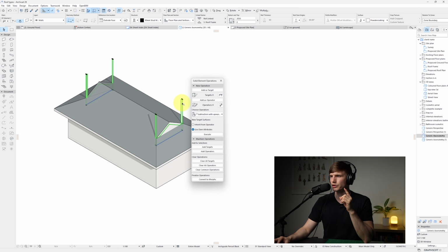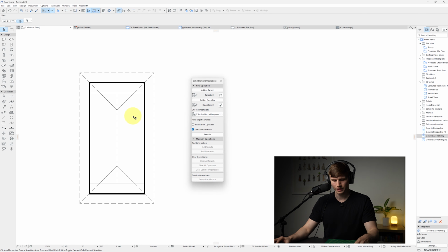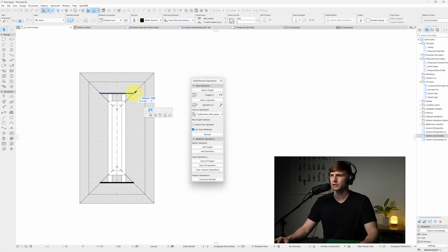Now we've got these little leftover bits just on the sides here, from where the wall is slightly outside of that gable. If we go into our 2D view, and then holding Control, go up, and press the up key. If we select our wall just here, we'll click the edge node, and with stretch selected, we'll hold in Shift and we'll drag this in until it no longer intersects with that line. For this, we'll go 200, we'll click enter, and we're going to do the same thing for each of those edges. We'll do the same thing for this one here as well, 200 and 200, and hit enter.